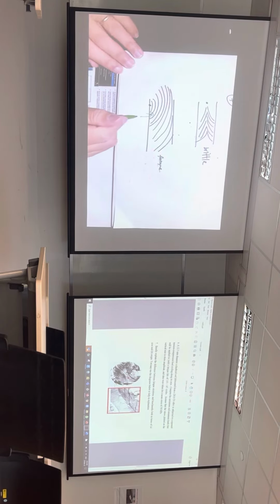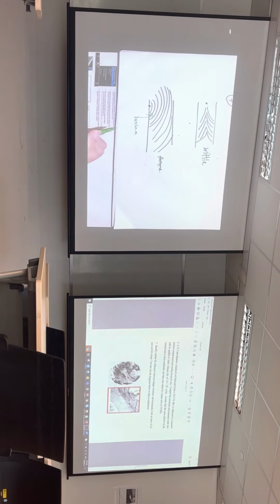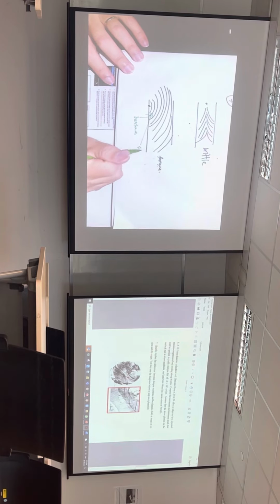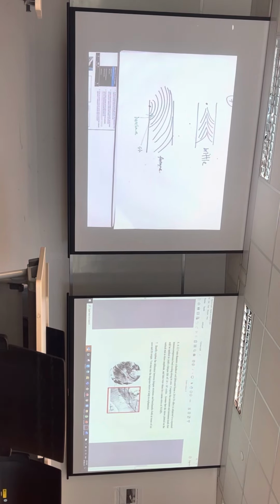The big lines are the beach marks, like big terraces, a paddy field. If you zoom inside here, you start to see striations, from smaller loadings, also fine lines radiating the same way. So in this picture, there are the big ones and then the small ones.